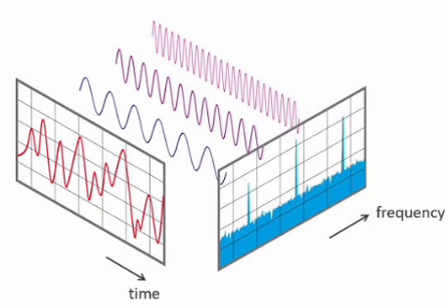For energy signals, the Fourier transform of alpha of tau gives the energy spectral density, that is, alpha of tau transforms to F of omega times F conjugate of omega, the ESD of F. For power signals, the Fourier transform of R F of tau gives the power spectral density. R F of tau equals the limit as T tends to infinity of |F T of omega| whole squared by T, the power spectral density of the function.